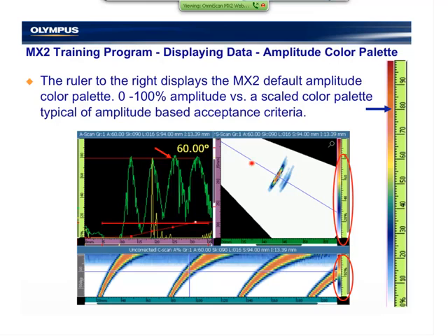When the beam is properly calibrated across all of the angles in this axis for one flaw or side drilled hole, and it's also calibrated in TCG for time of flight, this allows the entire beam to have a consistent color palette across multiple TCG points.